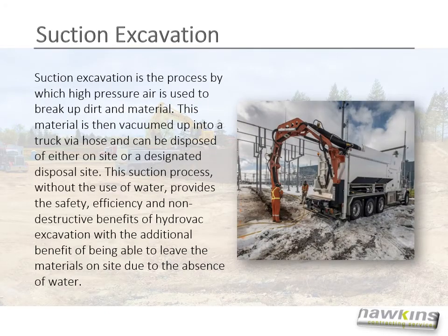Suction excavation is the process by which high-pressure air is used to break up dirt and material. This material is then vacuumed up into a truck via hose and can be disposed of either on-site or at a designated disposal site. This suction process without the use of water provides the safety, efficiency, and non-destructive benefits of hydrovac excavation with the additional benefit of being able to leave the materials on site due to the absence of water.